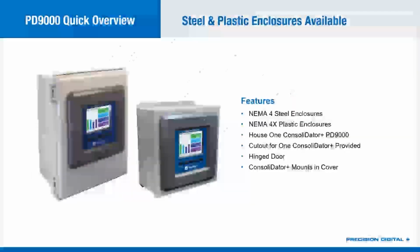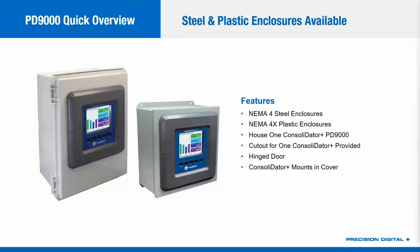And though it is not strictly the ConsoliDator Plus, it is worth noting that we do have a line of enclosures for these products. So if you want to put it in a panel, but you don't have the panel, well, we offer a line of NEMA 4 steel and NEMA 4X plastic enclosures, where the X, by the way, is corrosion resistance. So though it is a painted steel enclosure, theoretically, steel rusts, and therefore it doesn't have the X. But that's why it's only NEMA 4 for steel and NEMA 4X for plastic, and plastic is corrosion resistant.